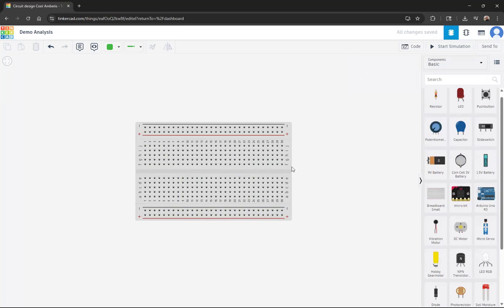So we've started with a breadboard. This first circuit I'm going to do is going to be fairly simple. It's just a resistor circuit, and I've got a diagram here in front of me that I can work from. I'm just going to click a resistor and drop it in place. With it selected, I'm going to flip it because I want it to resemble the diagram that I have here on my paper. So this resistor I'm going to draw here, and I'm going to double click it.